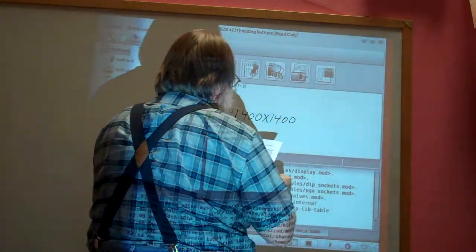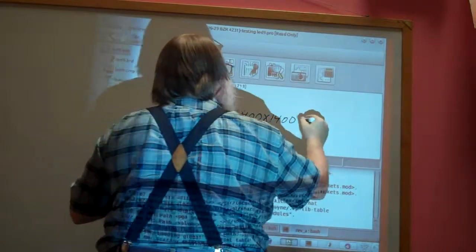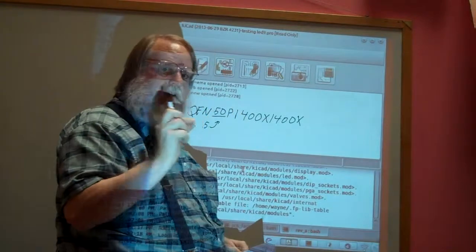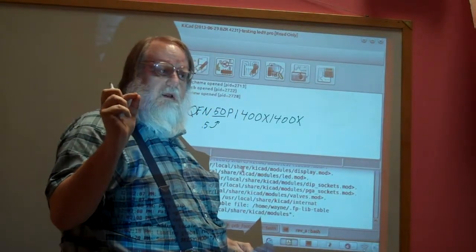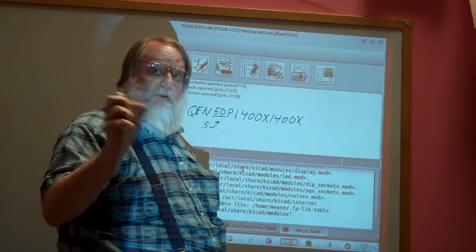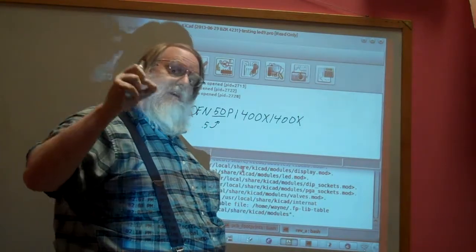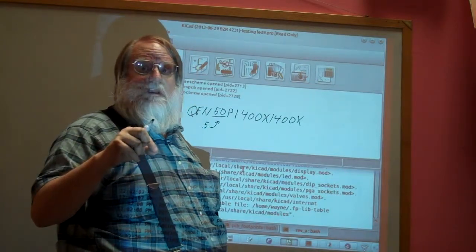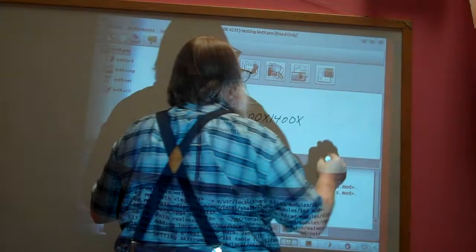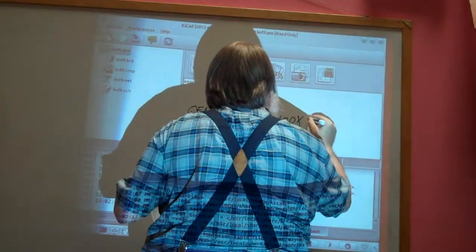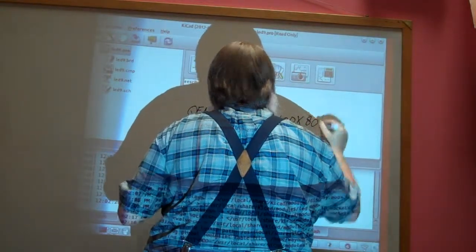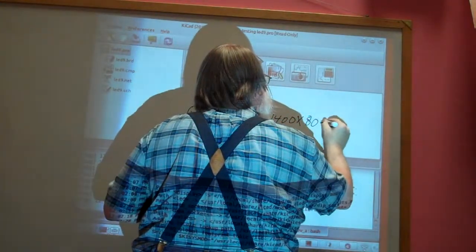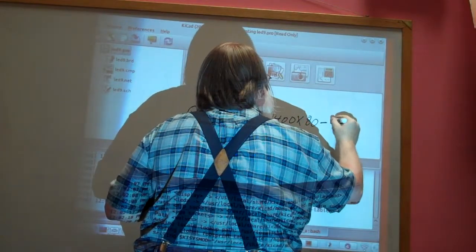And then you have height. Now, height is not technically needed for the printed circuit board part of this stuff. But if you need to do pick and place at a later date, the pick and place machine needs to know how high everything is. So you put a height on here. I'm making this up, I'm going to say this is 8. Then comes the number of pins, and that's